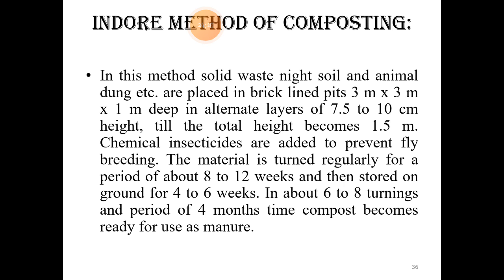These trenches or tanks are filled further with organic solid waste with 10 centimeters height, alternated with the soil and animal dung waste. The system is left for a few weeks. Later, between 8 to 12 weeks, the material is turned so as to get the complete compost.